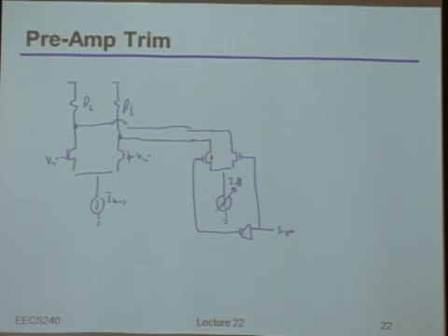That's true even dynamically, meaning that even if there's a big cap sitting right here, as long as the RO of this device is pretty high, you don't really care that there's a big cap sitting here, right? It doesn't really load your high-speed output. So this is actually a really, really nice trick to make it so that you can push that DC offset cancellation thing, even though it's going to have extra capacitance and parasitics, to not really significantly load your high-speed signal path from a capacitance standpoint.